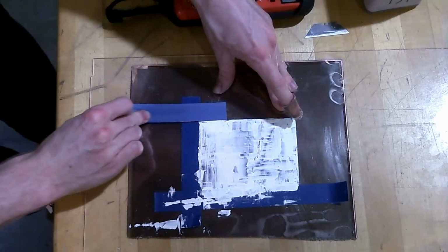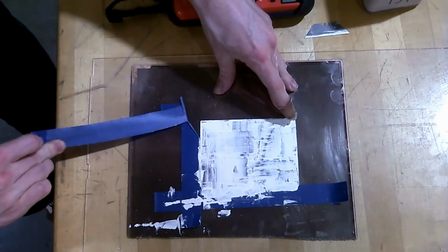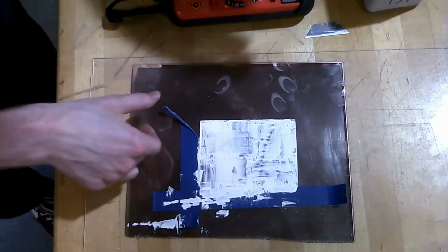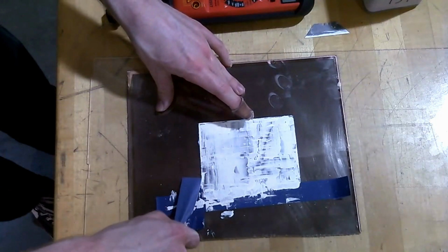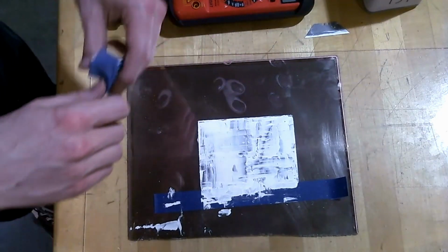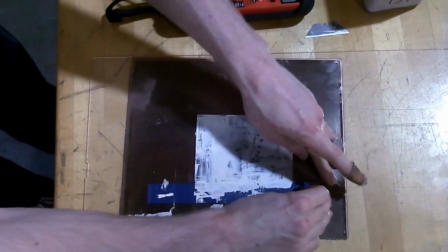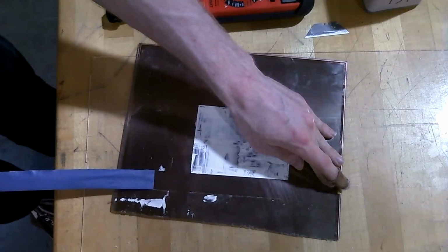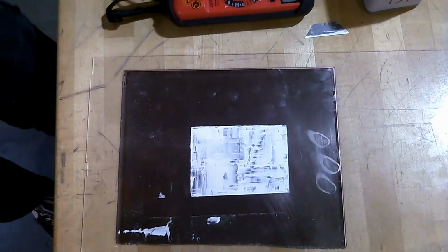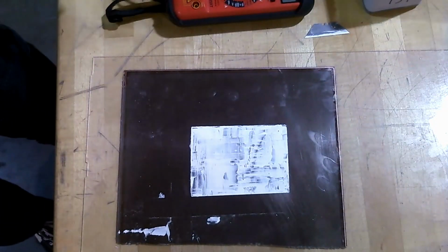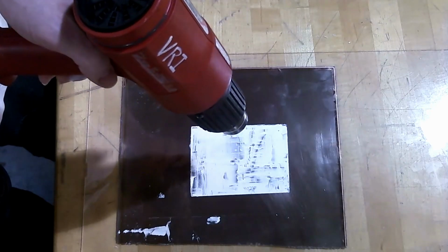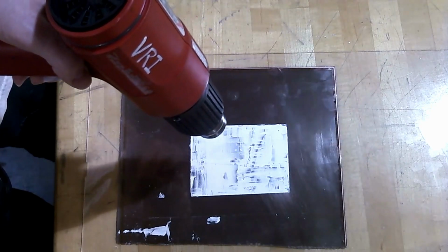In this process, you'll see that I use a heat gun in order to sinter it. The small problem with that being I did this over a layer of acrylic, and it did melt the acrylic underneath, which is not desirable, and it did burn to the back of that layer of conductive glass. It should be kept at this 450 degrees for 15 to 20 minutes, which is the optimal time.